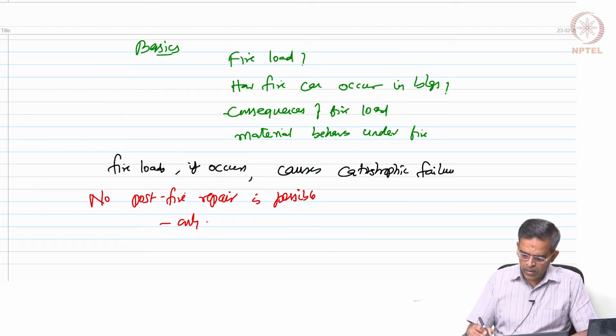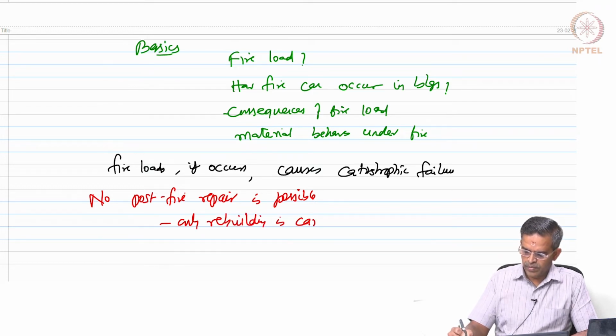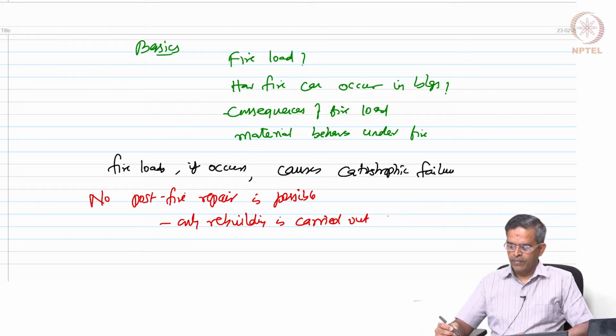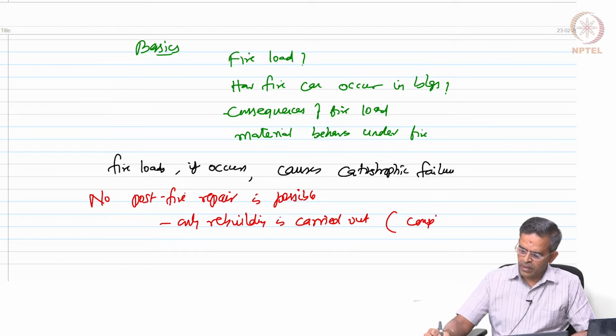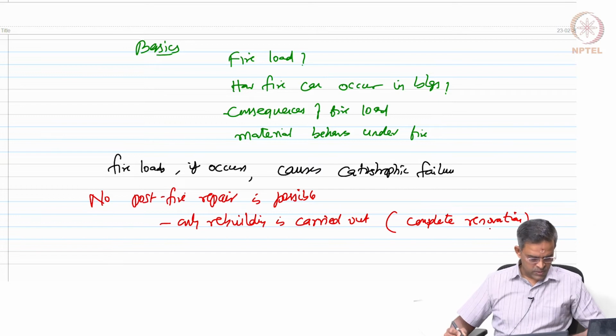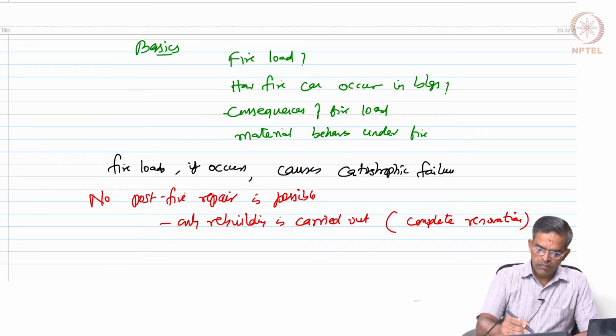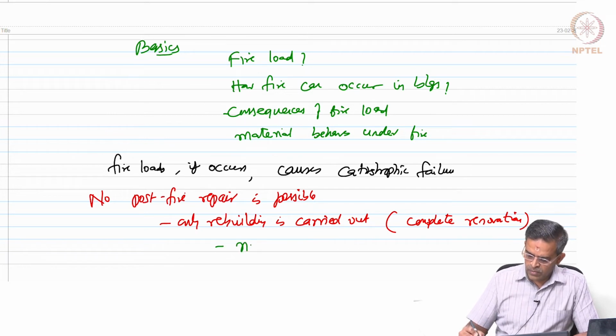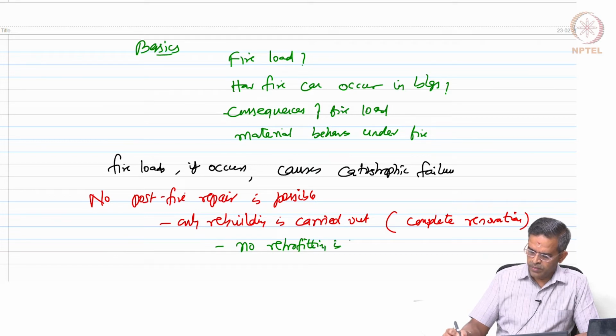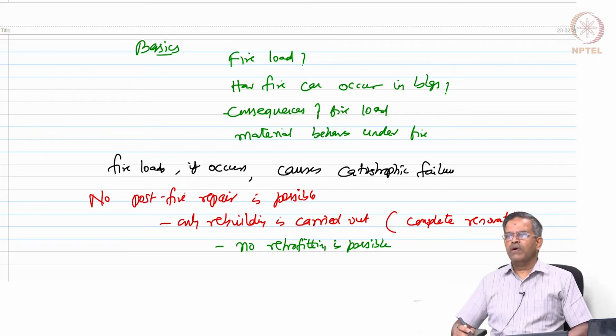Only rebuilding is done, no repair. It is amounting to a complete renovation, because fire causes a total devastation. Okay. Very importantly, no retrofitting is possible for structures subjected to severe fire loads.